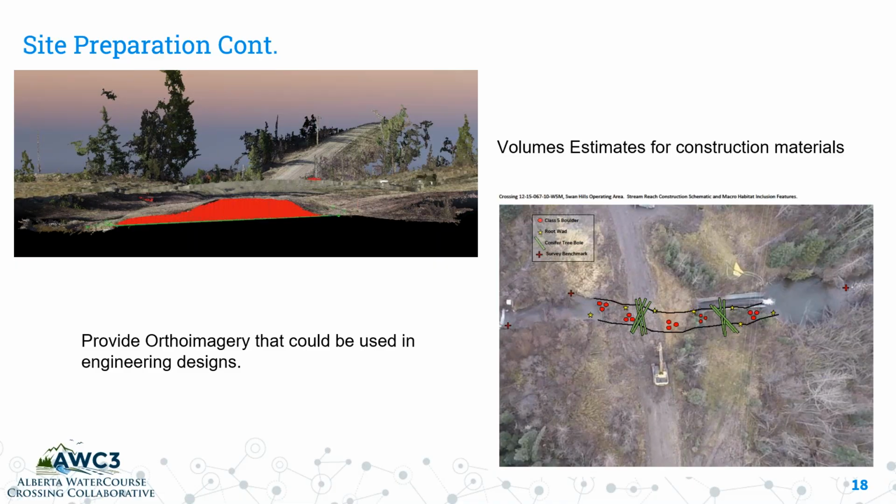It also helps me understand how much materials I'm going to have to buy or purchase to either backfill into that new roadway watercourse crossing, or how much material I'm going to have to transport out of that area as well.